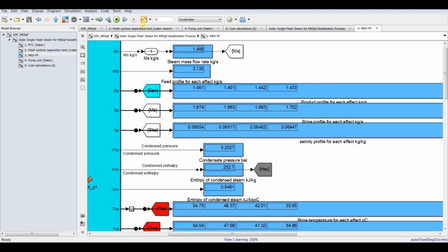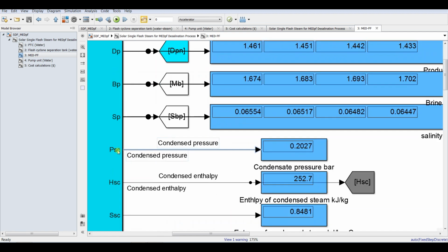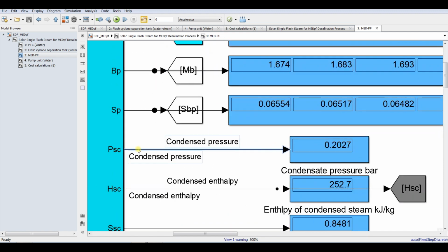Suppose I need to discover this. You have to click here on this signal. Suppose I need to discover the result or export my results to the data inspector. So you have to click here and click on stream selected signals to data inspector. You can select this option.